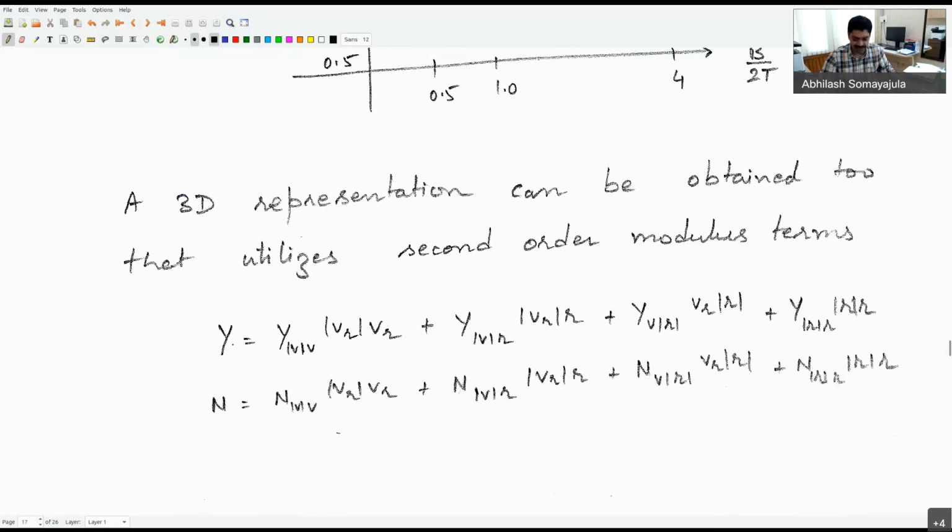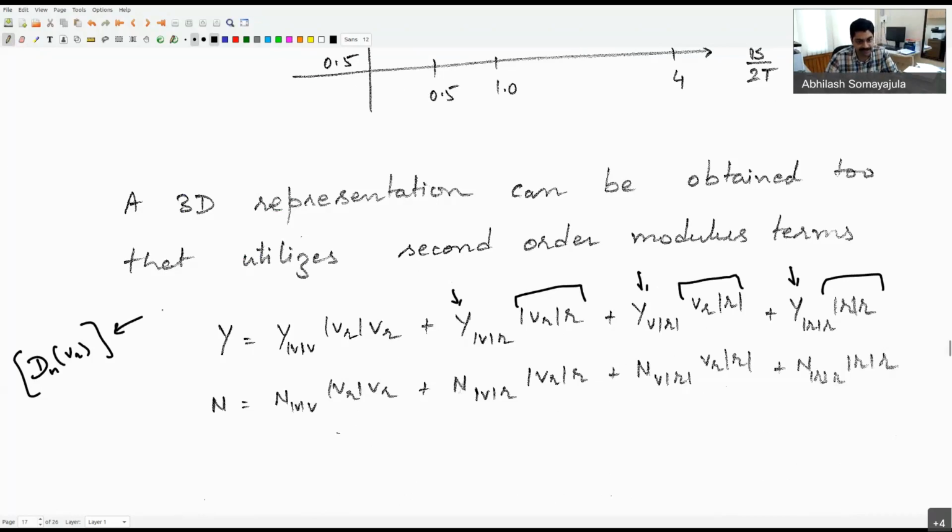As I said, finally, we can do the same thing as we did with the surge. We can express that force as some nonlinear damping coefficients times these quadratic terms, and then evaluate what these coefficients are. Once we get these coefficients, we can put them into our nonlinear damping matrix. That is where they'll find a place.